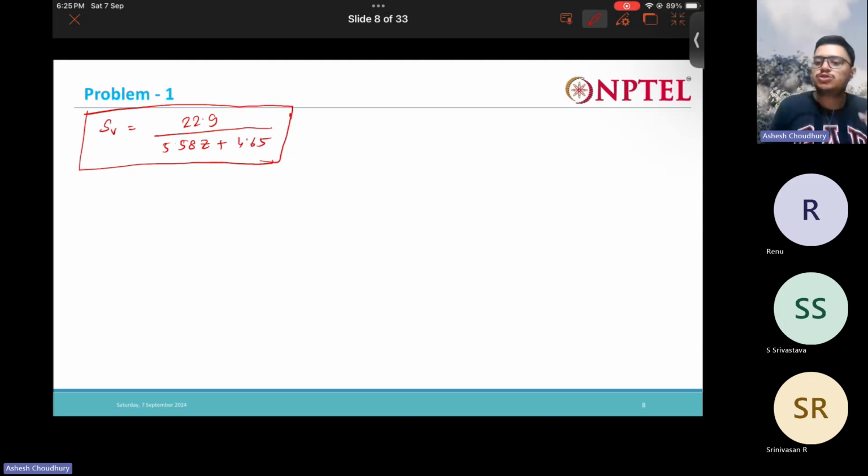Now in the question it was told that the SV is kind of restricted for us. Why is it restricted? It is restricted because the height of each of these precast concrete facing blocks is around 1 meter. So our spacing is kind of restricted. Let us see for 1 meter spacing, till what depth can we put it safely. Let us check that first.